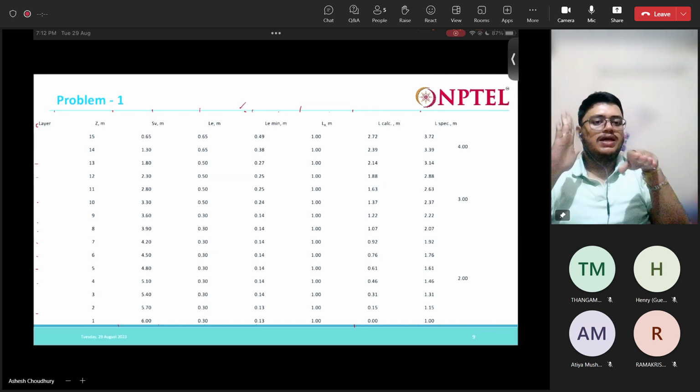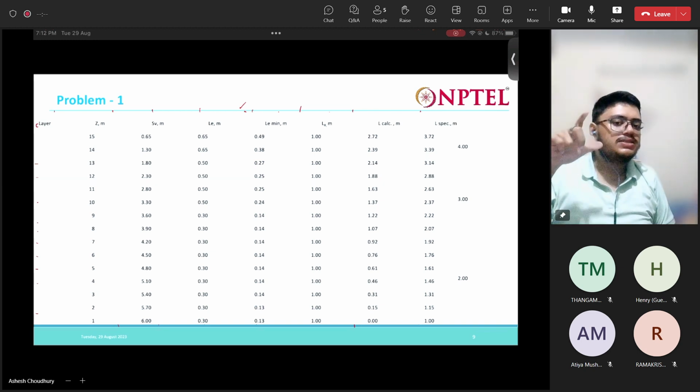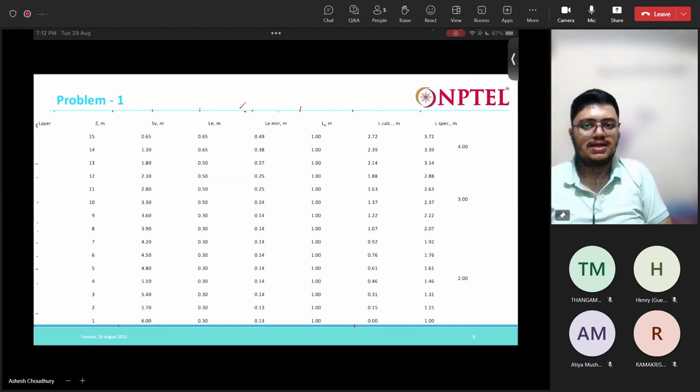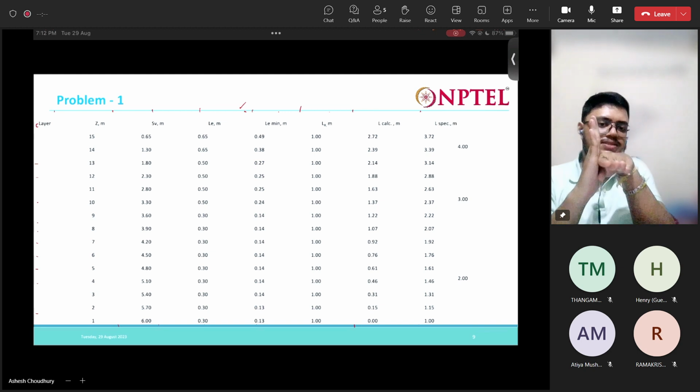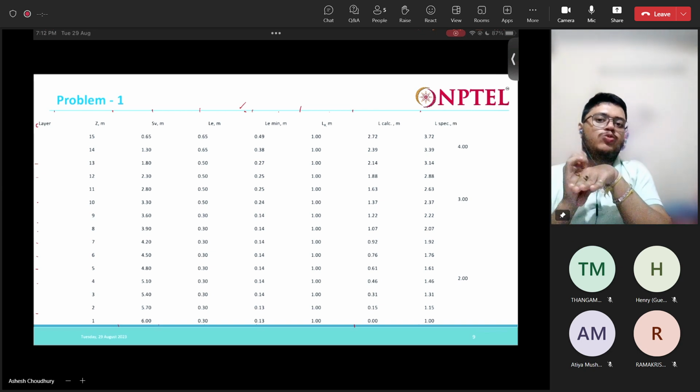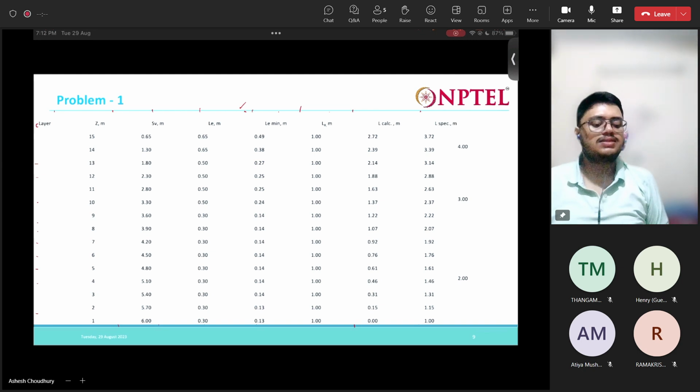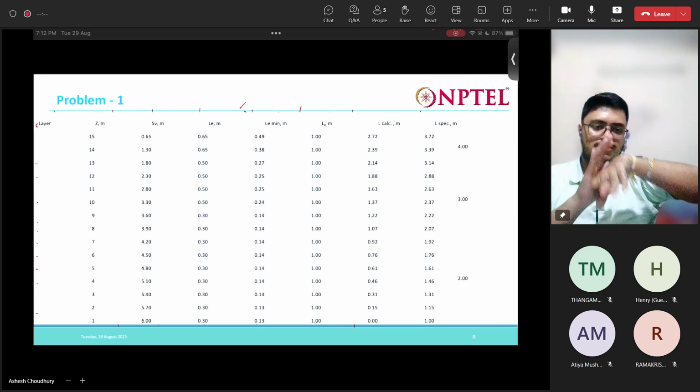If the calculated length is less than the width, then we can also place the geotextile like this. In that case, the weft direction, the cross machine direction strength will be utilized. But generally the calculated L is greater than the width, so generally it is placed like this only and not like that.